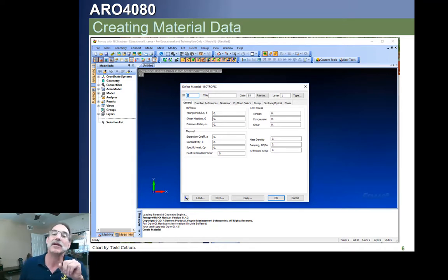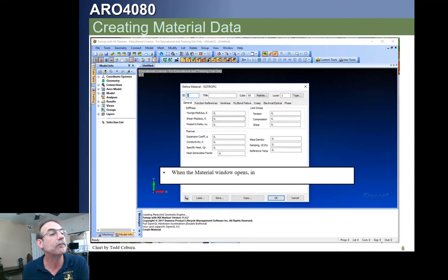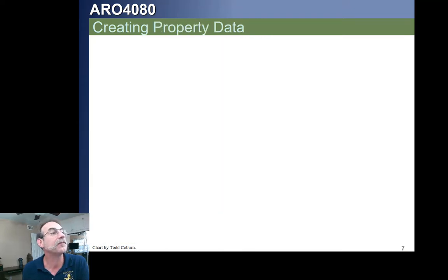If you wanted to later calculate stresses or margins of safety, now we're not going to do that yet, but if you wanted to, then you could put your allowables in for that material as well, like your FTU and your FCU and your FSU, okay? Your material density, you mostly aren't going to need unless we go into dynamic loading, but you can put that in, and sometimes NASTRAN will struggle if you don't have it, even though it doesn't need it. So you can go ahead and put in a little density value here. You aren't going to need damping or a reference temperature for this stuff until we get to thermal analysis, and you can throw in a reference temperature, okay?